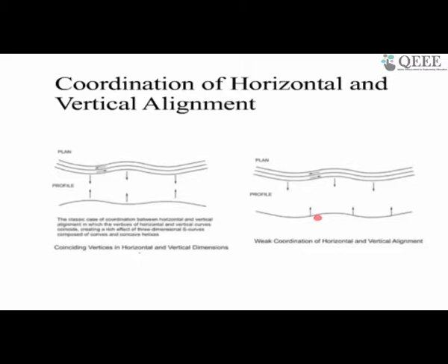We should remember to provide the horizontal curvature right on top of the vertical curve, or right before the summit curve, not on the other side. So this is what we are coordinating. If we move it to the other side, it is going to be difficult. You have to consider the roadway going from one direction to the other, so you have to consider traffic on both sides.